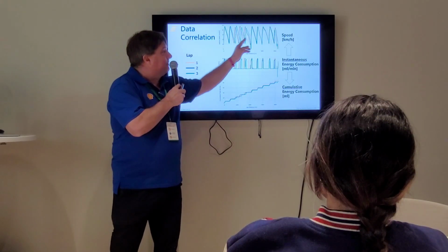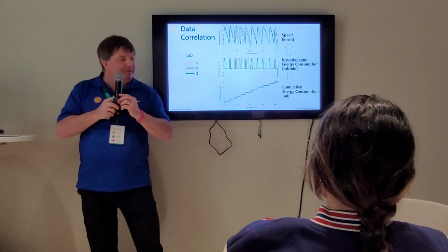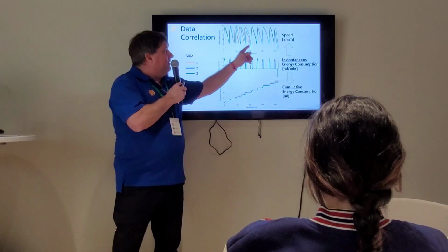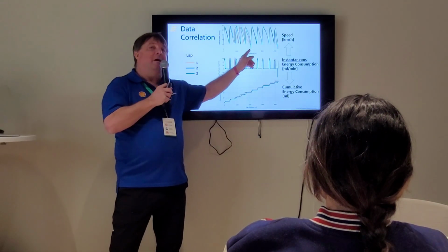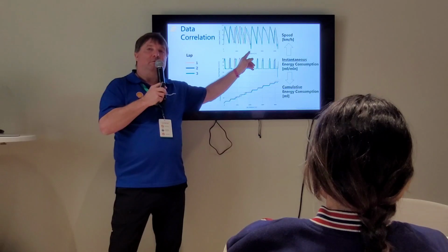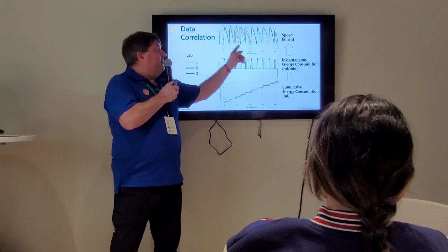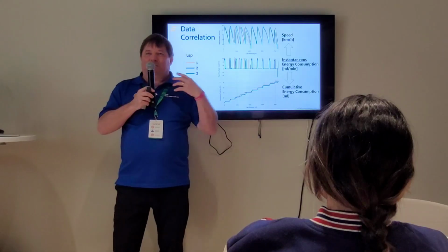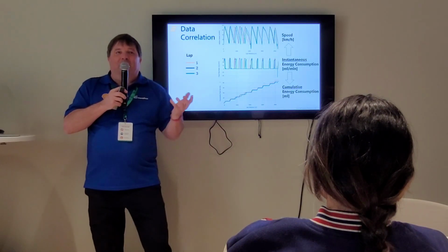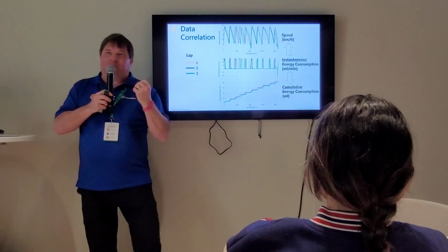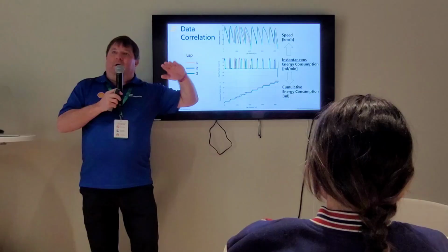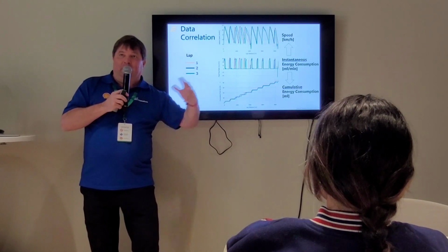What you can see here on this track, this was actually some data that Ian was creating for us. Here you see speed goes to 0, so this is actually half, a right half in the middle of the track where you have the mandatory stop. And I was telling him, if you do your burn and coast, don't do it consistently. Just play around a little bit, with no intention. And in the second one, try to be as precise as possible. Try to remember at what point you hit the throttle, and at what point you coasted, until what speed, and then to regain speed again.